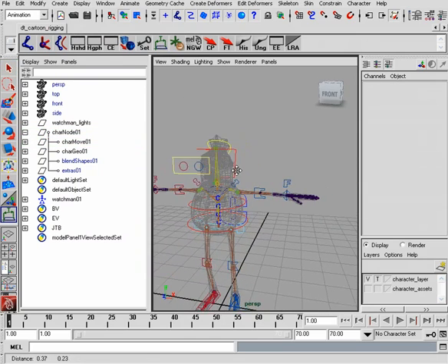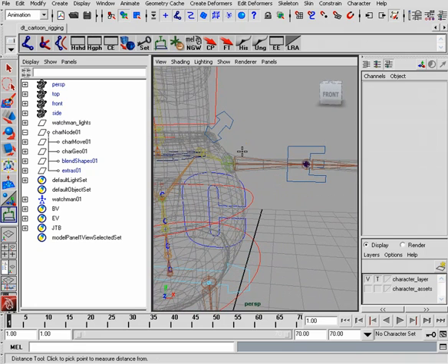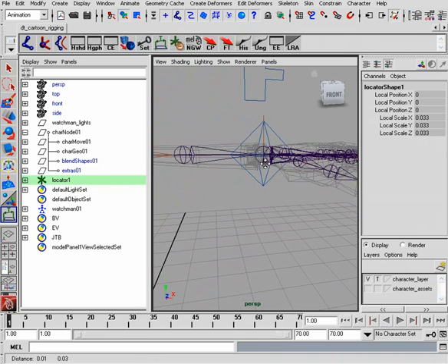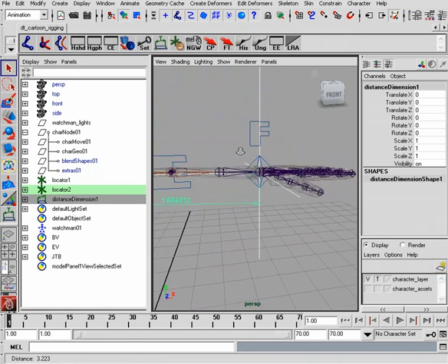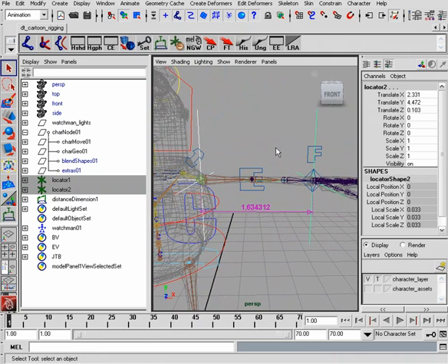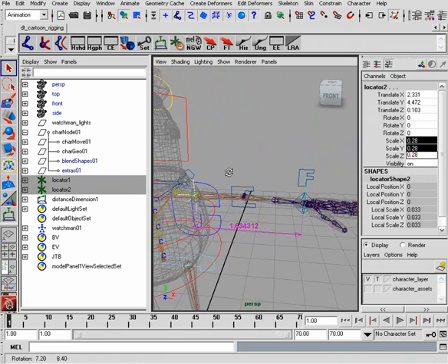We'll go to our distance tool now and work on adding our locators. So we'll hold V, vert snap. Of course, we'll just start with the left arm, work on these locators, and then we could apply them to the right arm as well, moving back and forth between them till they're all set up. We'll select our locators, switch their size, 0.28. It also works, that's good.